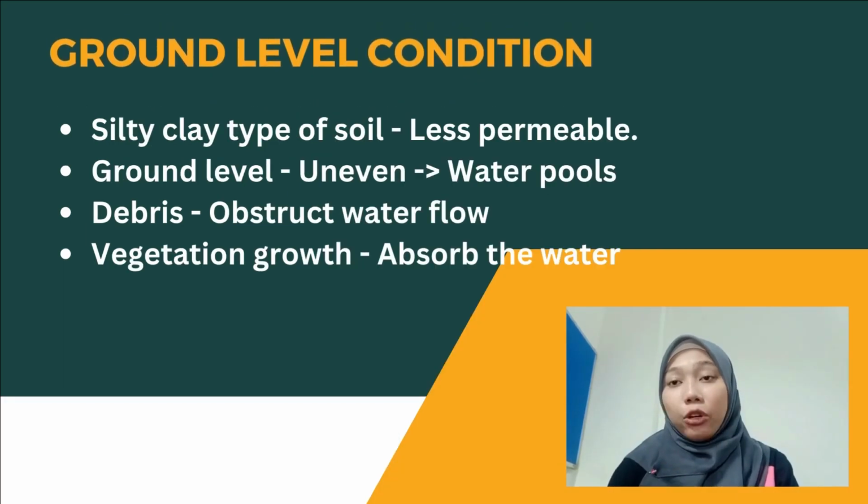Now, I will continue the presentation by sharing with you all about the ground level condition. Based on the channel observation conducted, we notice the type of soil can be classified as sandy clay, which is less permeable than sandy soil. This means the ability to allow water flow is low.